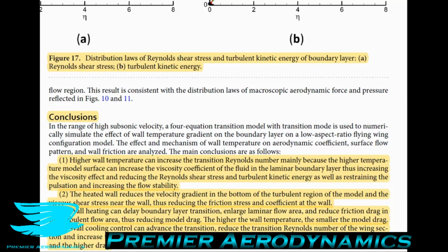So when that happens, you actually want to have a more turbulent boundary layer. The reason is that if you have a more turbulent boundary layer, the flow near the wall is faster. And that's what you need to overcome the adverse pressure gradient. The adverse pressure gradient, which is just a pressure gradient pushing back on the flow upstream, decelerates the flow near the wall. Once you decelerate to the point where the flow is moving in the opposite direction, it has to separate because there's nowhere to go. It has to just go straight up.